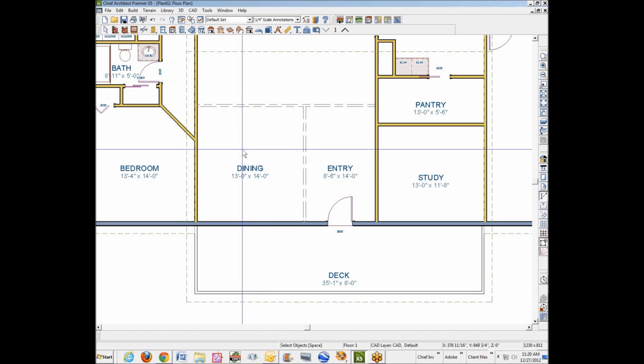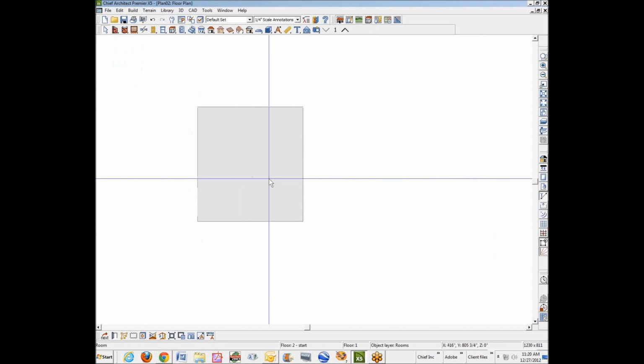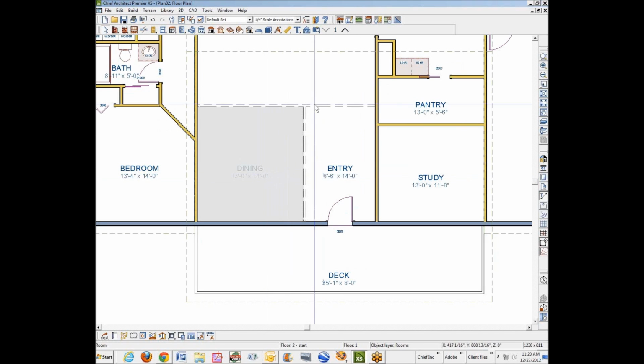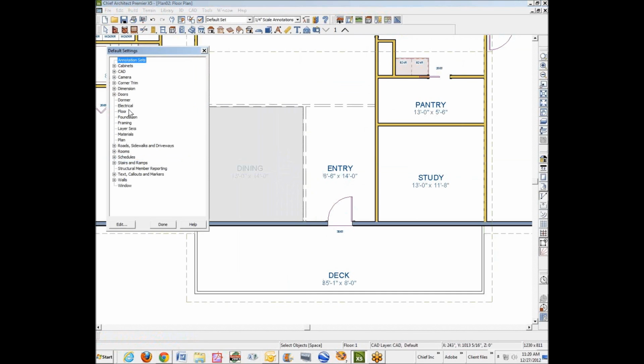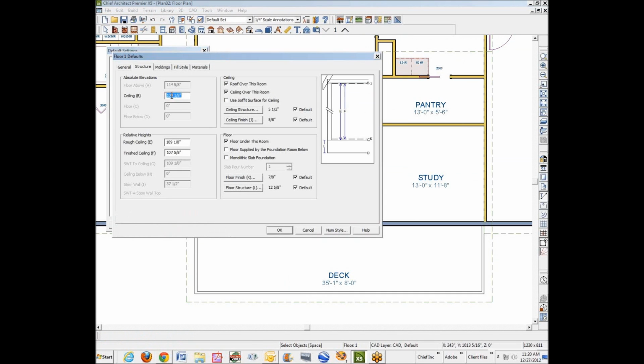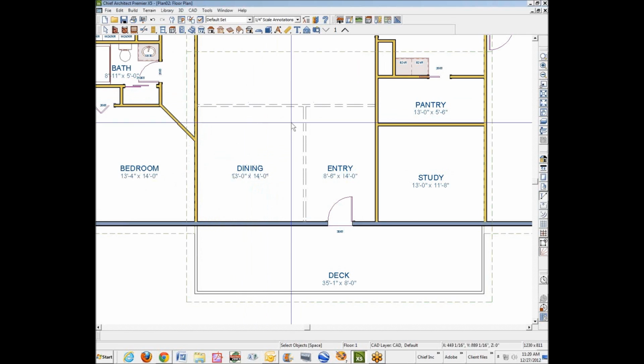Let's see what you have the ceiling set in here. 9 feet. So you didn't say how you're going to coffer the ceiling, etc., so I'm going to have to guess. I assume then you set the floor to kind of sort of 9 feet. I don't know why you use a ceiling of 107 5/8. That's your business. Okay. I'm just going to take it as it lays.